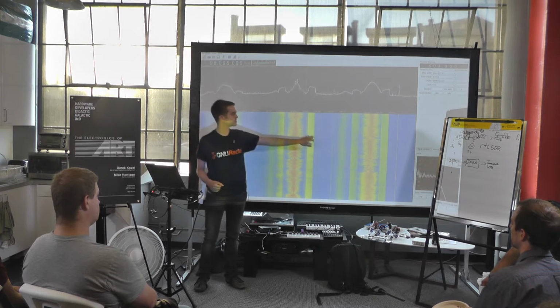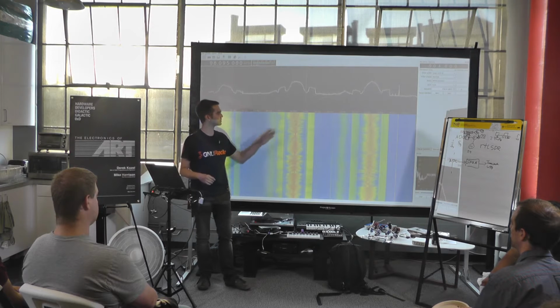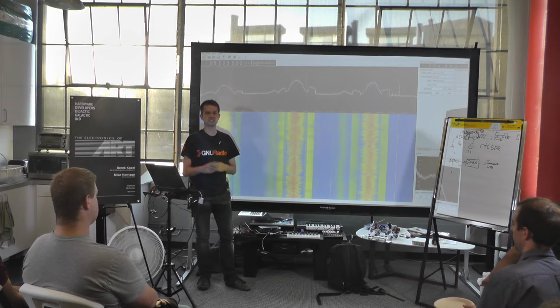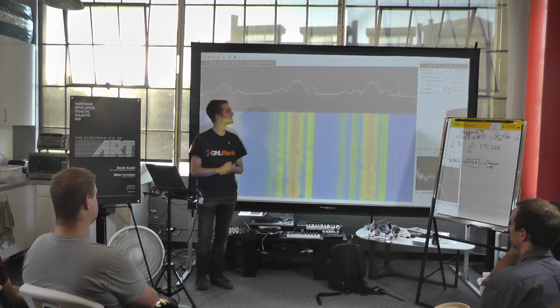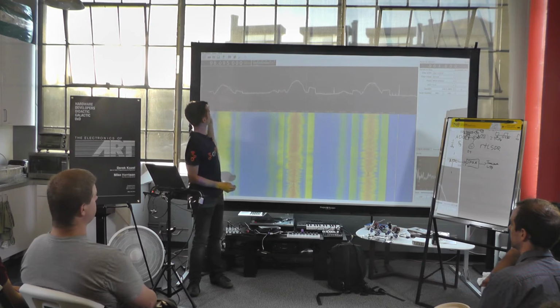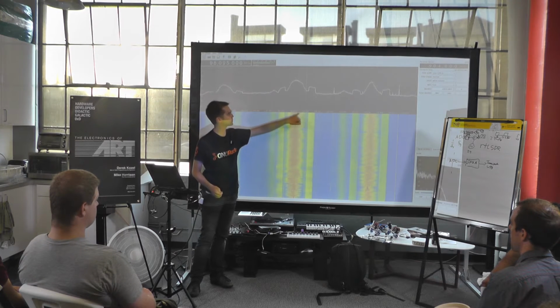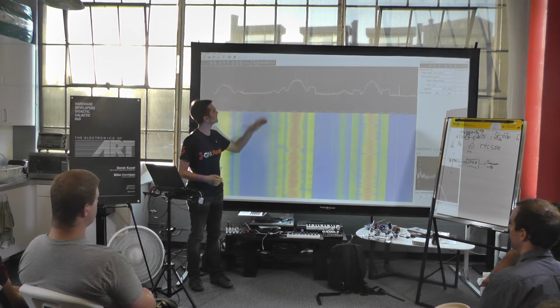On the side here, you can see the digital audio sidebands. So if you have an HD receiver, you can actually tune in here and get some information. And it also carries RDS information. So this is the information that tells your radio receiver, you're tuned to this station, this track is playing. And so what we're looking at here is frequency, marked out by these small numbers here. So we're tuned to 98.9, give or take.